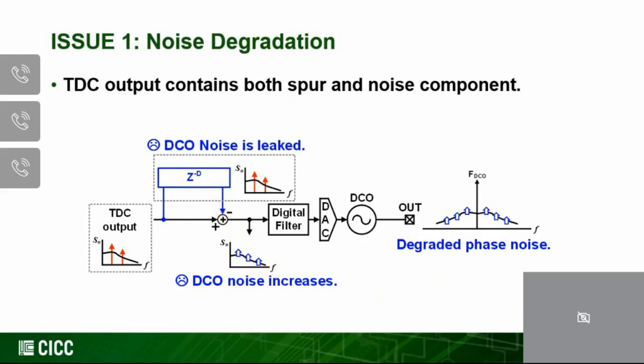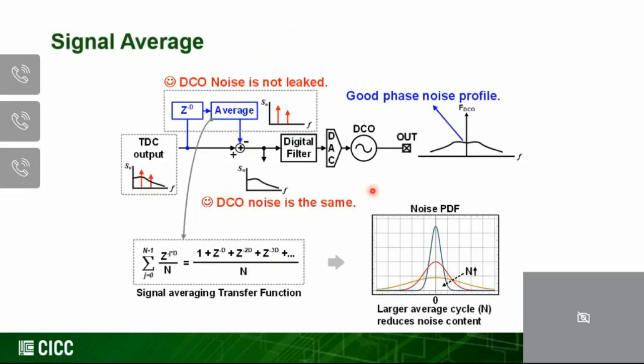So what should we do about this? Therefore, we propose to do averaging after this fundamental delay element. Once we do the averaging, because the phase noise here is random, assuming that we do enough averaging, which you can see here is basically just a simple add and divide by capital N, depending on how many samples we're averaging. So basically, we would average out this noise right here.